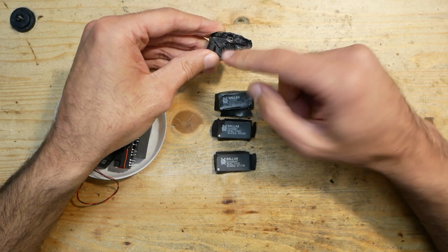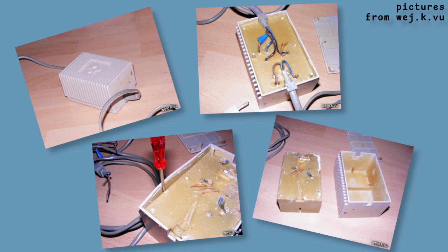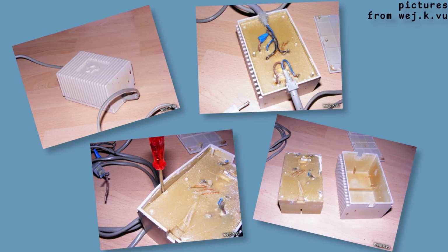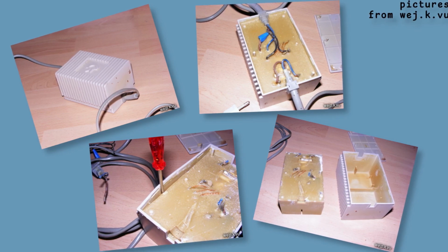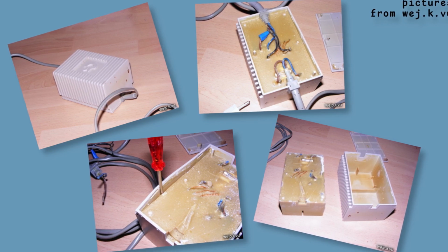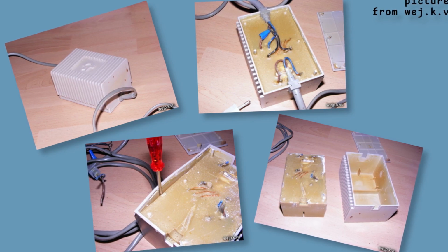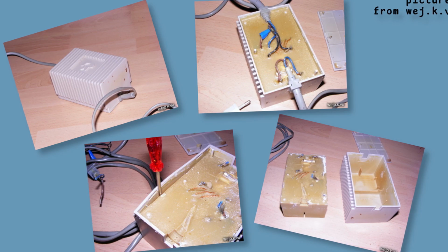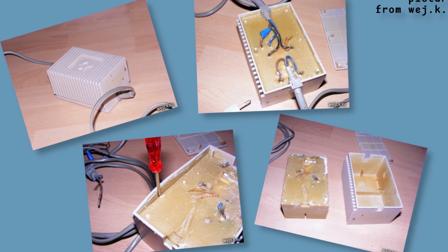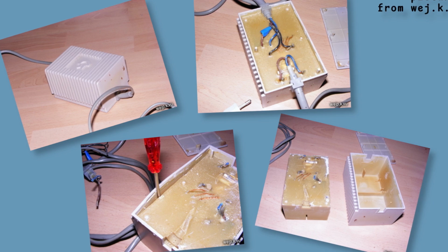By the way, as I did this and realized how easy it was, I instantly thought about the Commodore C64 power supply, which is notorious for its failing 5-volt rail. That power supply is usually filled with resin as well, and people don't even think of extracting the internals, despite the fact that the transformer is usually still alright and only the low voltage part has to be fixed. Taking into account how hard that resin is, that is fully understandable, but now, knowing how it reacts to heat, that could make it something easily doable. Probably for many of you this is nothing new, but for me it was quite a discovery.